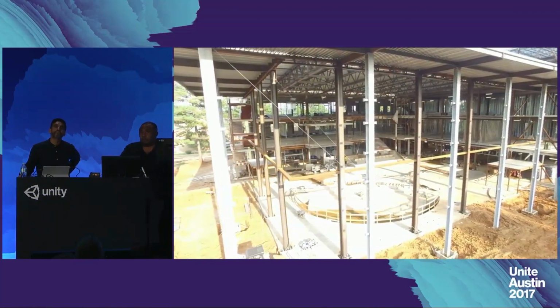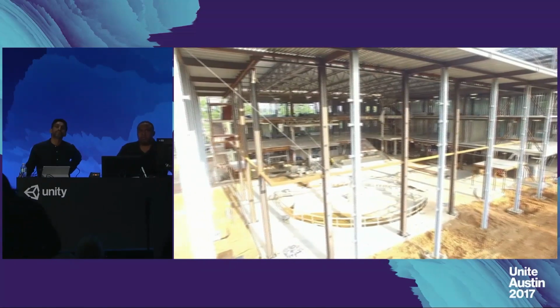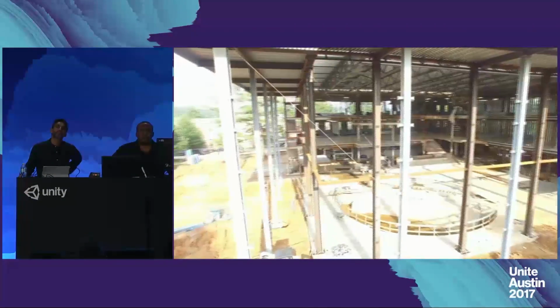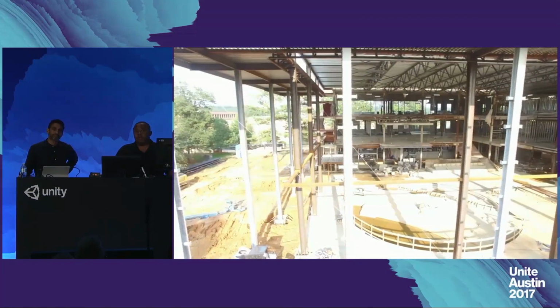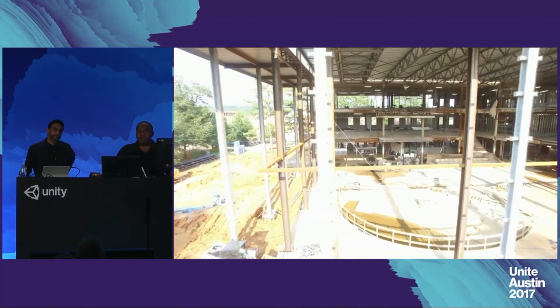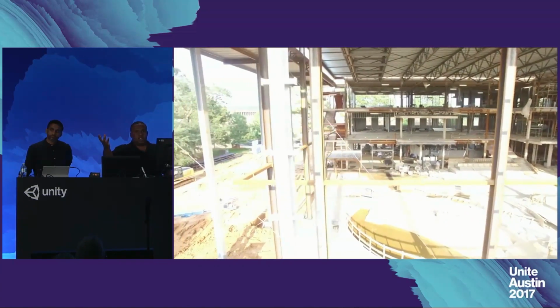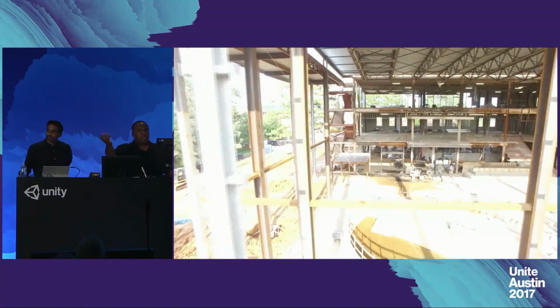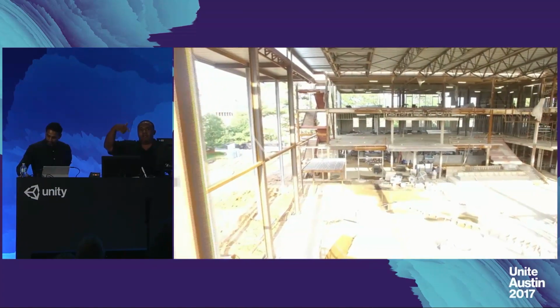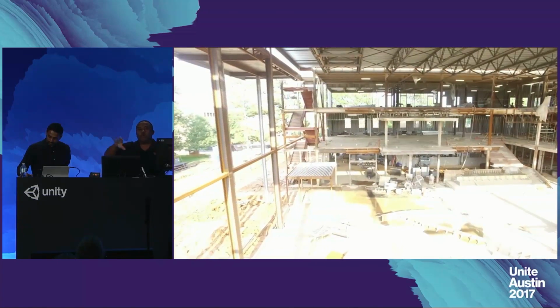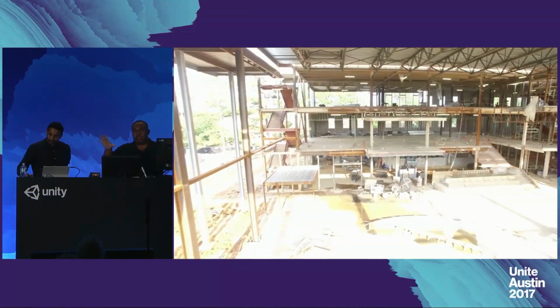So do the individual objects that you put into your Revit model come out into Unity as individual objects that you can then add physics to? Yeah, they do. All the meshes related to that object have been grouped and ordered, and the object even keeps the same object name and element ID code from Revit, which opens up a lot of opportunities when you're designing your own active functions within Unity.